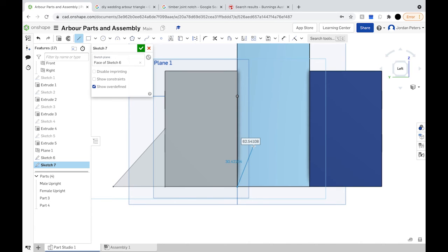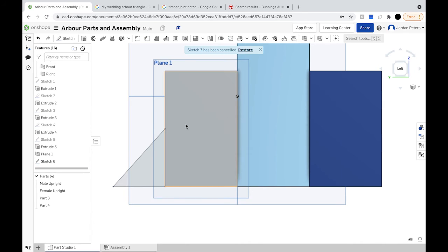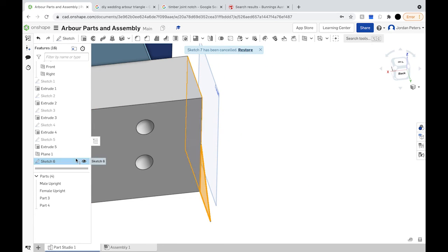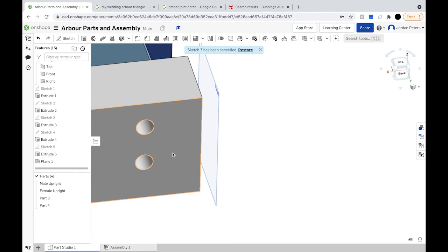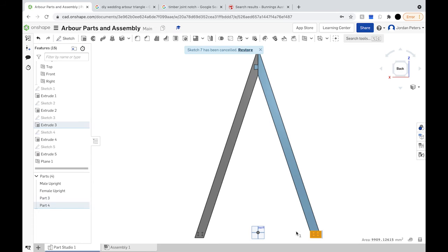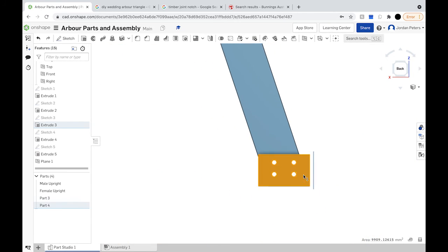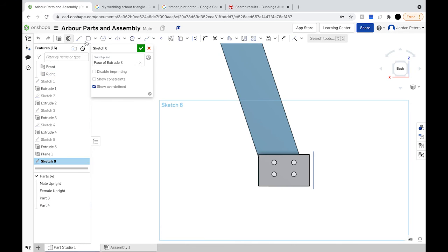There might be a better way of doing this actually, because that decimal is quite long, it might just keep going and might technically not actually connect to the object. So I might do a different way, but at least we know that skill of offsetting a plane. We can delete that sketch we just did as well. Alright, so let's go off this face and go back. Sketch.